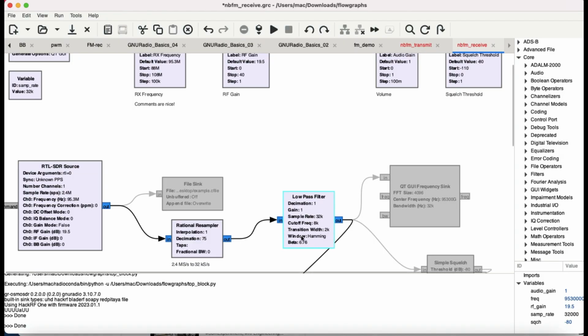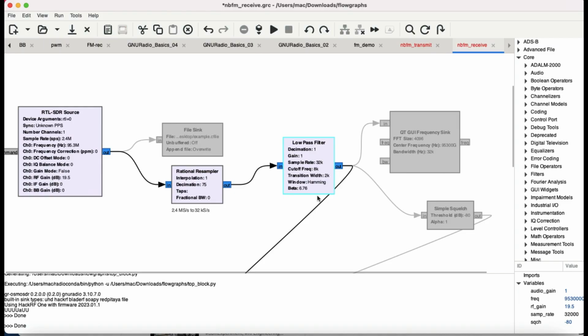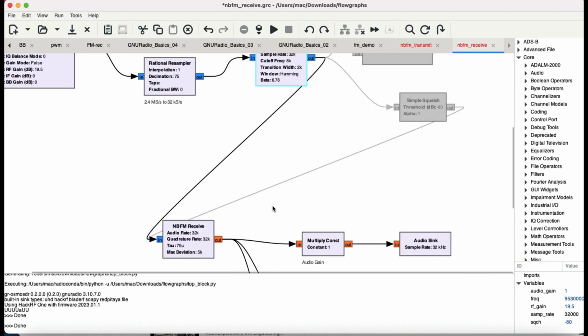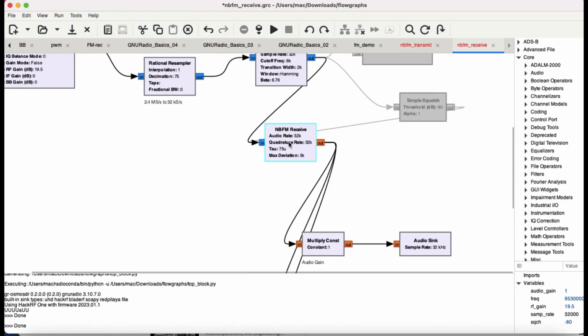And here's the part of what I was saying earlier. Remember, the low pass filter has a cutoff frequency of 4K. Now when you start sampling at twice of that, this is going to be 8 kilo samples, and this is what we generally do in telephone lines as well. That's why you sound different on the phone than when you're speaking in real life. So this is going into a low pass filter. That's why I have set this to 8 kilohertz of cutoff frequency.